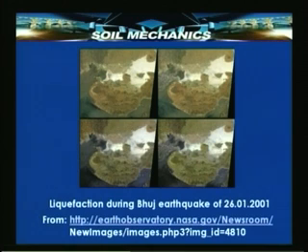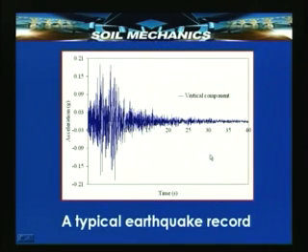Now, this can be used to understand and predict liquefaction in a very ingenious way. This is a typical scenario that was found during the Bhuj earthquake on 26 January 2001. This shows large scale flow of soil, and this is exactly what is known as liquefaction. And this is the earthquake spectrum which produced this kind of a liquefaction.